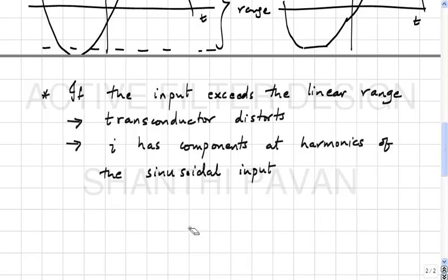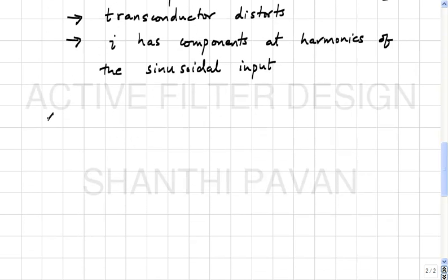Alright. So, if every transconductor has a linear range, it must follow that if I build a network with many such transconductors, that resulting network will also have a range of amplitudes beyond which something bad happens somewhere inside, and therefore the output is distorted. You understand?